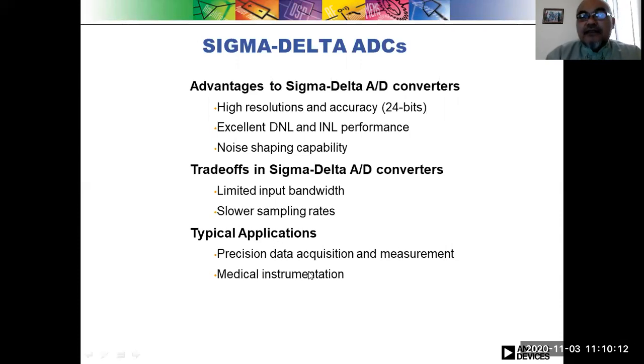Most medical instrumentation can use sigma delta ADC, but for imaging they require faster converters, especially continuous imaging, 4-dimensional imaging. It is now quite common to have 4-dimensional ultrasound, which can image not only 3-dimensionally the body, but also successively with time. How does the structure inside the body change? This requires a different, faster ADC.